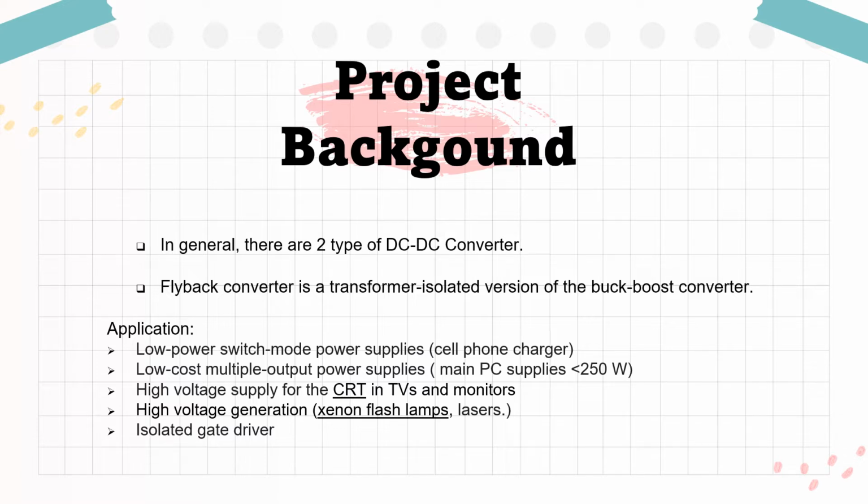Flyback converter is a transformer isolated version of the buck-boost converter. Flyback converters are commonly used in applications that need high-frequency voltage signal. Flyback is often used in low-power switch-mode power supplies such as phone chargers and computer standby power supply. Flyback may also be utilized to create a low-cost multiple output power supply with a maximum power of 250 watts.